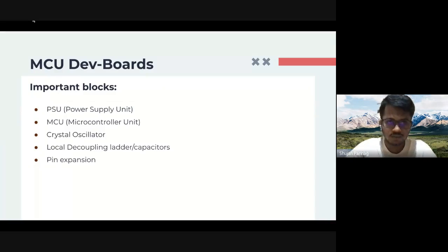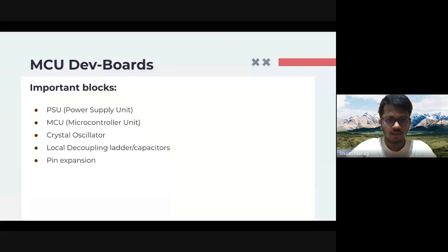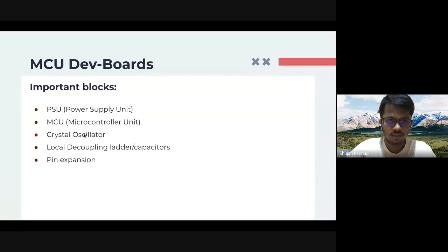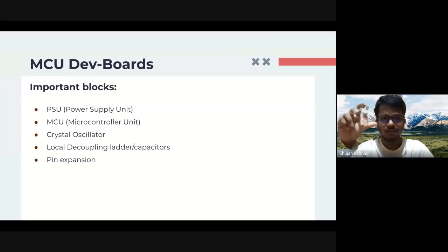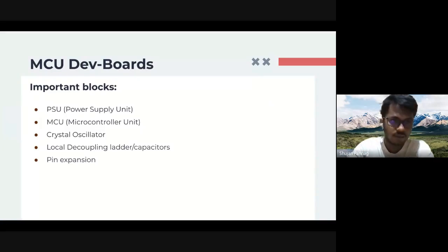No microcontroller works without a crystal or an oscillator, right? The Arduino has a Pierce oscillator, so we need an external crystal for the 180-degree phase shift. We'll go through that. And then noise is not always present at just one part of the PCB. It's almost present everywhere and can get induced anywhere in the PCB.